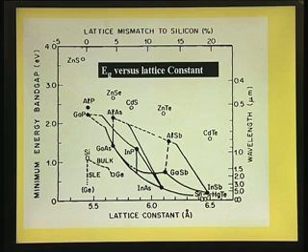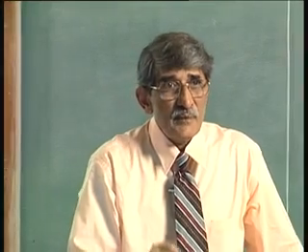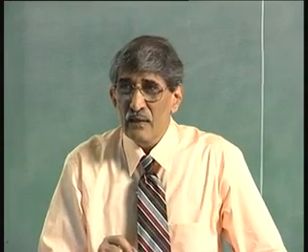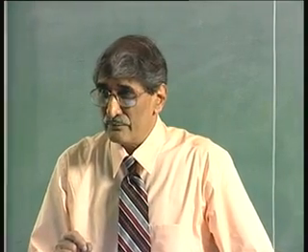On the right hand side, you see the wavelength. This is the wavelength that corresponds to the band gap. If it can emit light, it will emit light corresponding to that band gap, guided by the formula energy is equal to h nu.